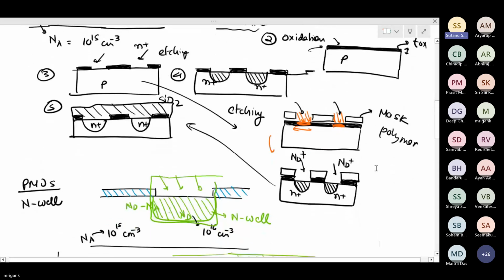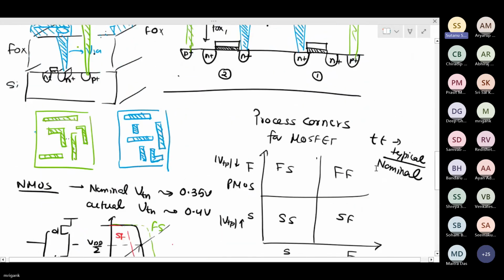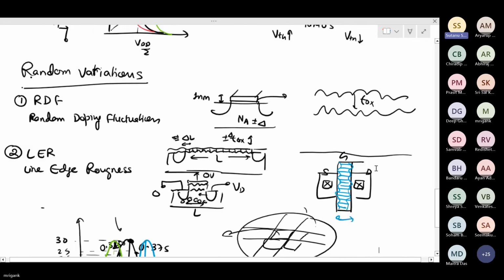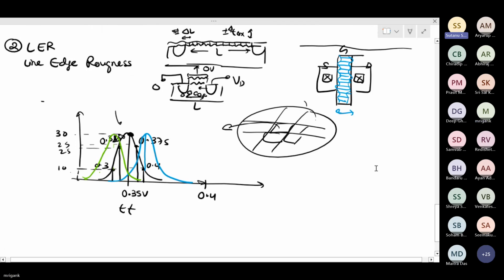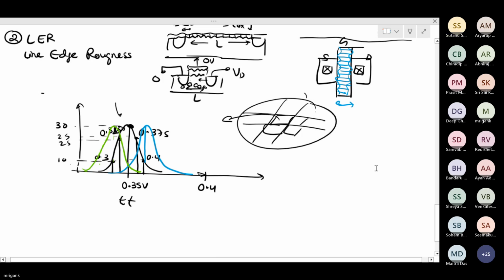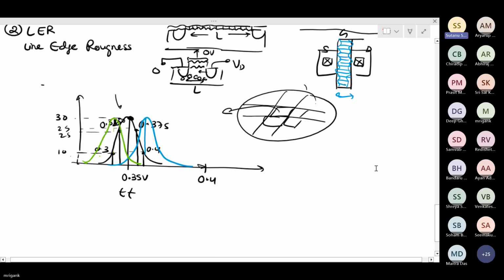Sir, I have a question regarding the last class. The last class, you taught how to build amplifiers using CMOS inverter, right? There we used a feedback mechanism, that is a high value resistor, to self bias the inverter. But my question is that if I bias the inverter using a current source, if I build a current mirror and then bias it using the current source without applying the resistor, then will it still act as the amplifier or will it have a lower gain? You can answer that part.